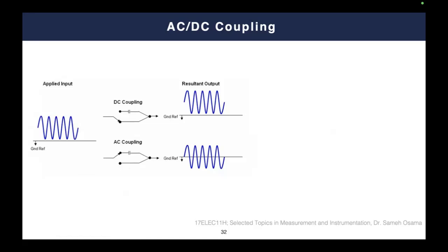Why does this happen? I think if you already remember our electronics lessons, you will remember this, or maybe you can already answer the question, because simply, whenever we have a capacitor, this capacitor has an equivalent impedance of, if you remember, my dear students, 1 over j omega C. So once this capacitor is operated in a DC manner, which means that the omega is 0, the equivalent impedance is infinity, which is typically equivalent to an open circuit.